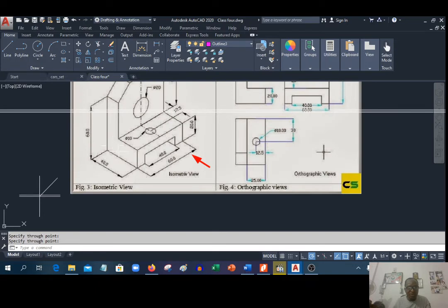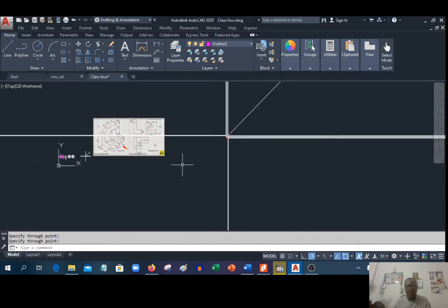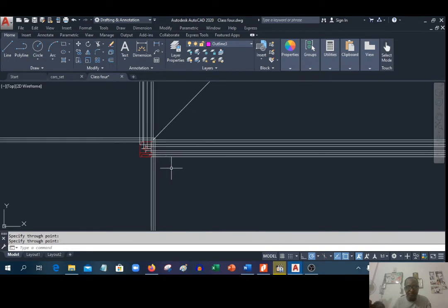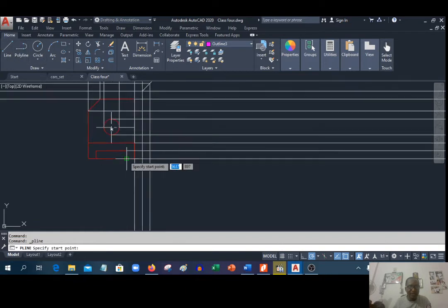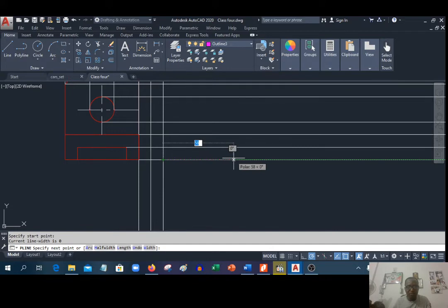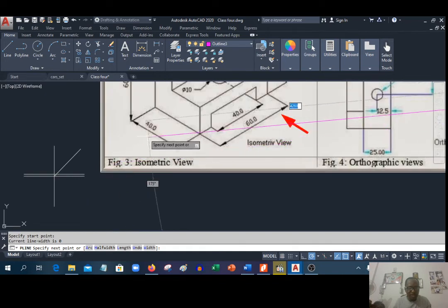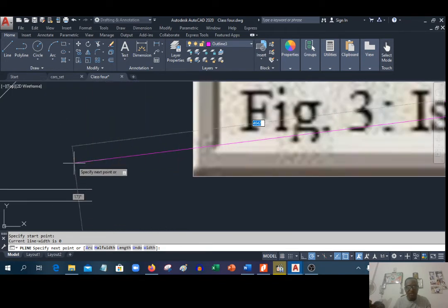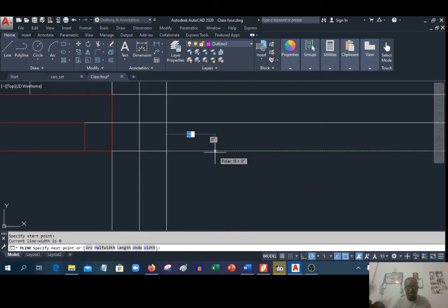So now let's come. The thickness of it from here down is 20, right? Then from here up 60 before we have the cross. So my drawing starts from this part. I'll use polyline. Let me start from the base here. I'll move this way. Sorry, let's see what that value is. For continue, that's 40. Let me scroll back and zoom out. So coming here, that's 40, 40, enter. Then I'll move up and stop here.